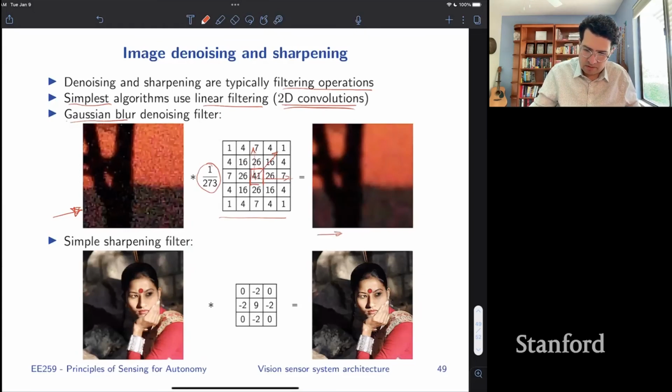So it gets the job done. You see, it's much less noisy in all areas. But also you lose some contrast, right? If you look at this portion, it's less sharp here. You get some blurriness, and that's also in the name of the filter. Because we're blending the value of neighboring pixels, we get a little bit of blurriness applied to it.